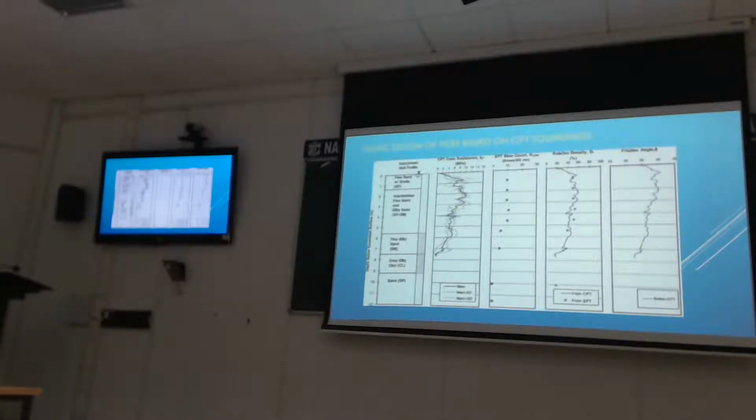Now, part of this may be due to pushing the cone too quickly and therefore generating positive pore pressures, especially in fine silts and so on. And this is why doing just the cone resistance is a bit iffy. If you have the pore pressure measurement with this, then that will tell you if the pore pressure is going up when you enter those layers, then this drop makes sense.